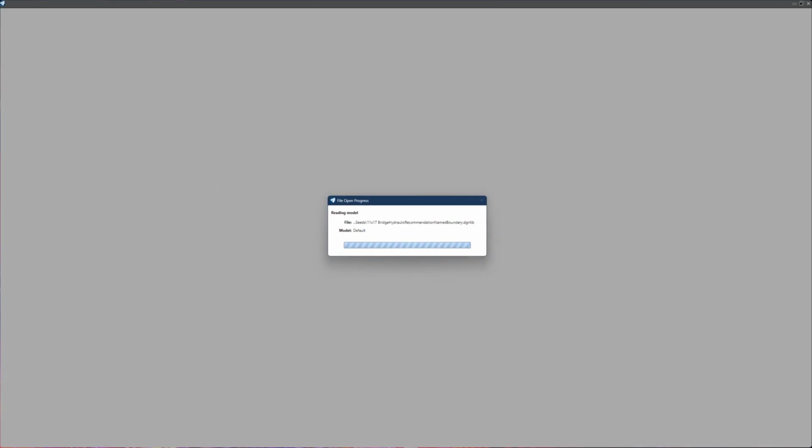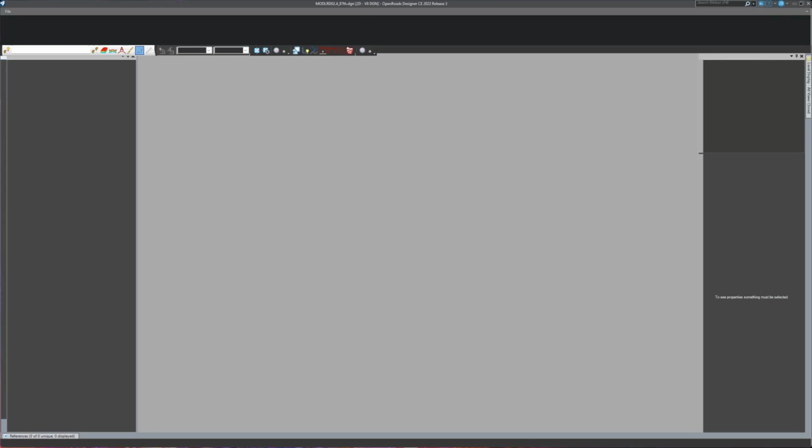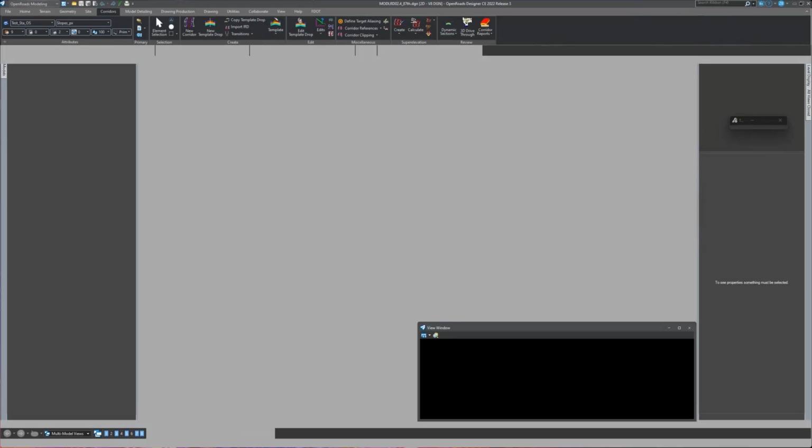I basically have similar labels and parametric constraints set up to allow me to dip that thing down and make it match the E curve. For me it's more like manipulating templates to get all that to work right. It's really hard to model a guardrail end treatment too. So usually I just show it all as guardrail up to the end of the end treatment line.